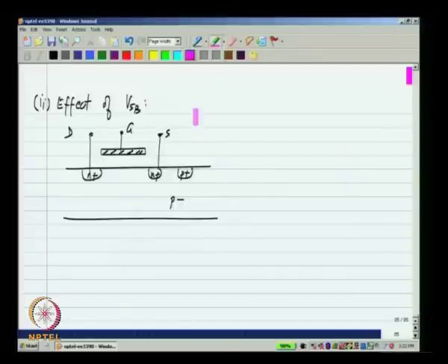Okay. Now, the very basic principle can be thought of as you have a capacitor between gate and this point, okay, gate and this region of the MOS transistor. If you raise the voltage across the capacitor sufficiently, you will form charges in the semiconductor, and that can be used for conduction.